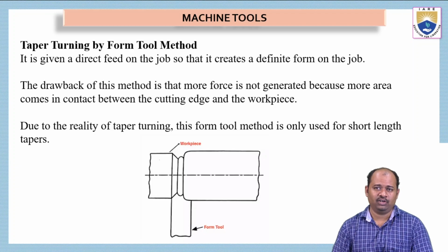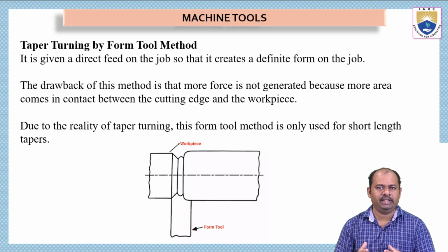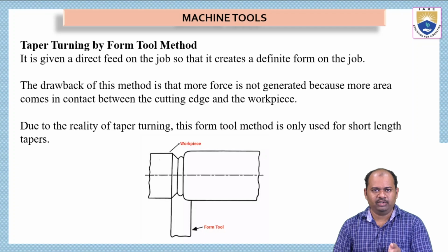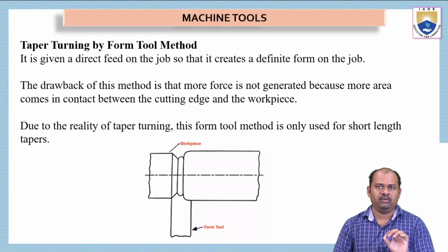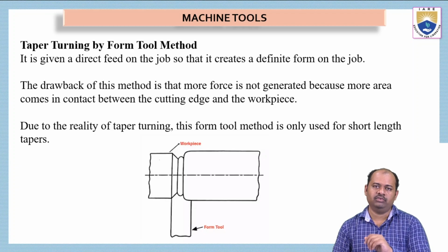But the advantage of this process is we don't have to worry about giving the feed. It will create the taper instantly and precisely. Because the tool itself is tapered and it has some taper angle, it will create the taper shape of the same angle. The drawback of this method is that more force is generated because more area comes in contact between the cutting edge and the workpiece.